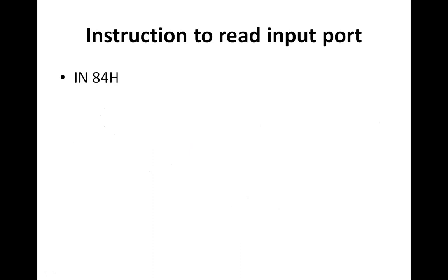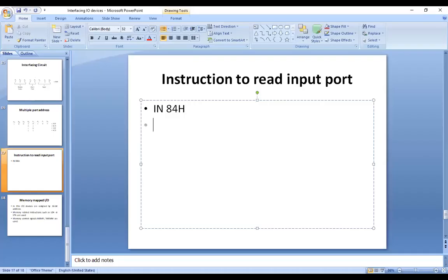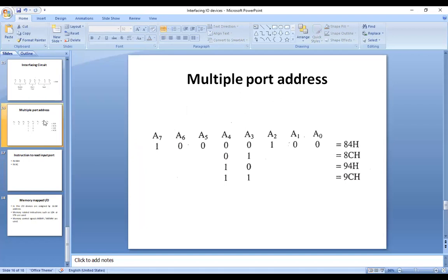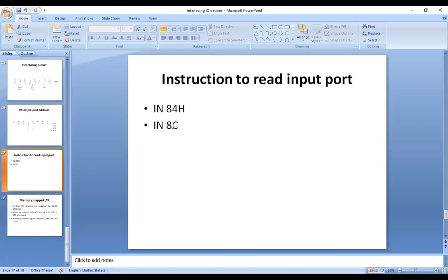So the instruction which can be used to read this particular input port may use 84, or 8C, or 94, or 9C.